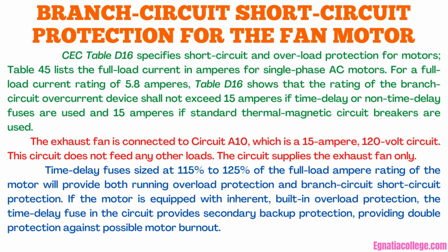Time delay fuses sized at 115% to 125% of the full load ampere rating of the motor will provide both running overload protection and branch circuit short circuit protection. If the motor is equipped with inherent, built-in overload protection, the time delay fuse in the circuit provides secondary backup protection, providing double protection against possible motor burnout.